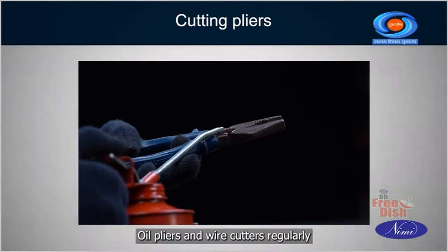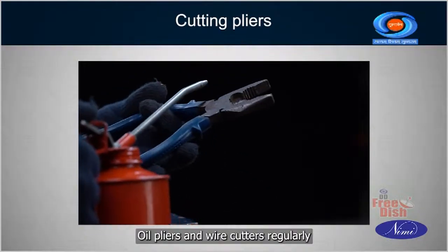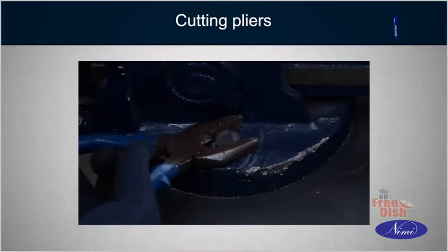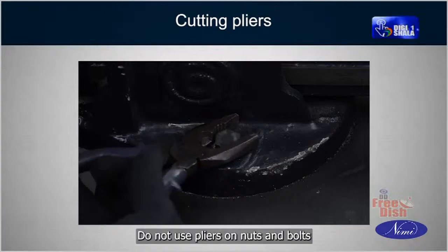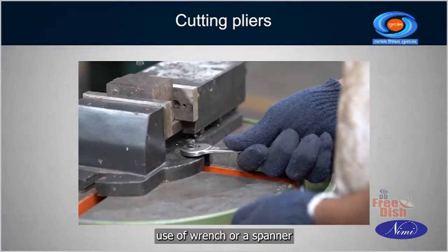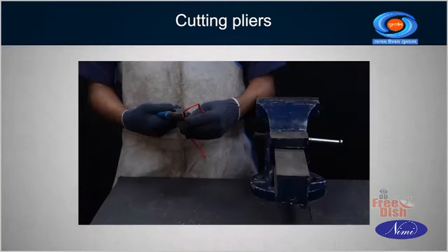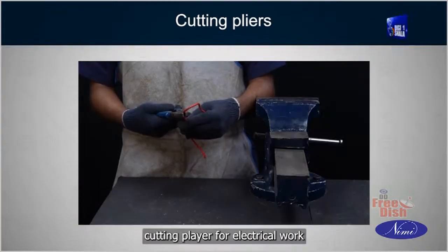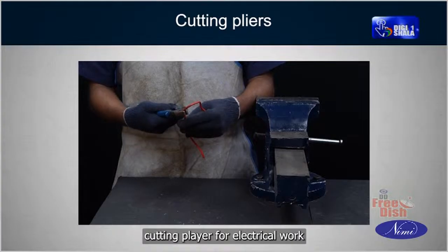Oil pliers and wire cutters regularly. Do not use pliers on nuts and bolts. Use a wrench or a spanner. Use insulated cutting pliers for electrical work.